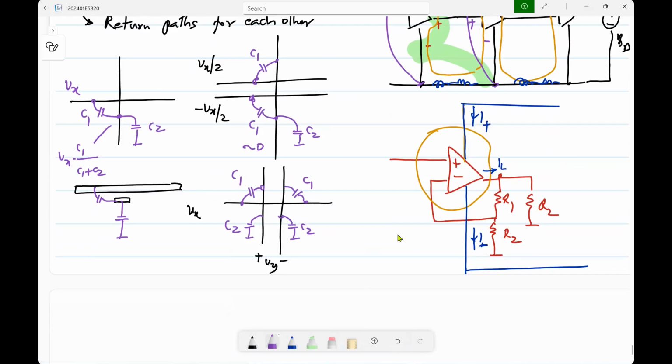It will also increase the complexity of the board, whereas on an IC, the fully differential circuit actually simplifies the circuit design. So it's almost always used. On a board, maybe you use it only when necessary. And typically, as you go to higher and higher frequencies, all these other effects start becoming more and more annoying, and you may have to use fully differential signaling. Okay. And this applies to everything also.